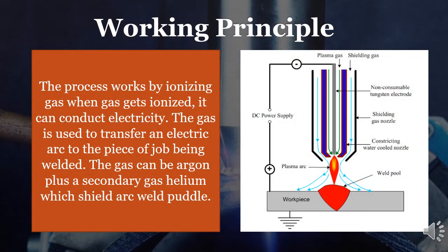Plasma arc welding is a process where a coalescence is produced by the heat, which is developed from a special setup between a tungsten alloy electrode and the water-cooled nozzle, or between a tungsten alloy electrode and the jet. This process employs two different gases for two different purposes. One gas is used to form the arc plasma, the second gas is used to shield the arc plasma. Plasma gas supplied throughout the nozzle turns into ionized. The shielding gas supplies throughout the external nozzle and protects the joint from the environment.